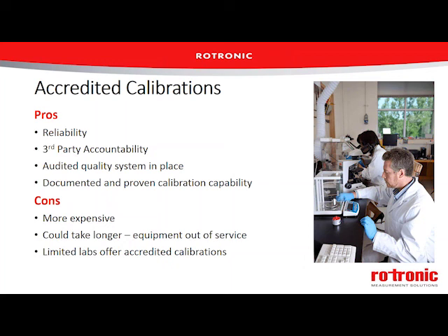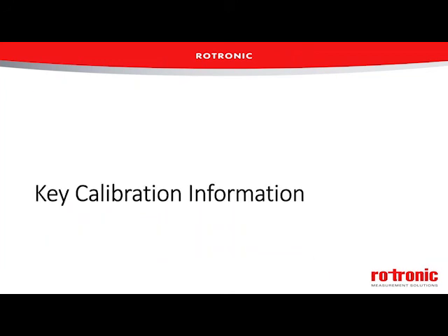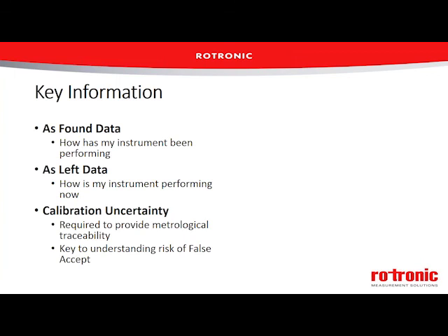They're not all the same. And there's a limited number of labs that are accredited, so you've got a smaller option of labs that can perform that accredited offering for you. Some of those labs may also be accredited for the field, but that's an even smaller number. So if you're looking for a field calibration and you want it to be accredited, your choices can be very limited.